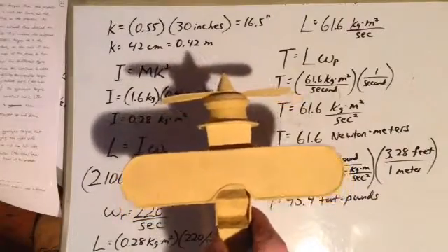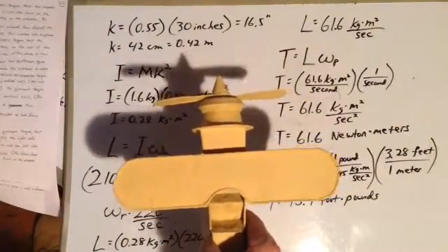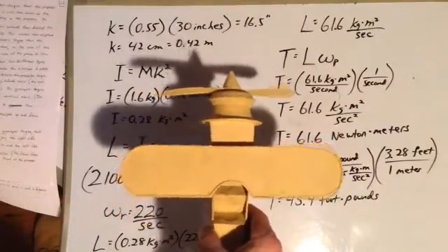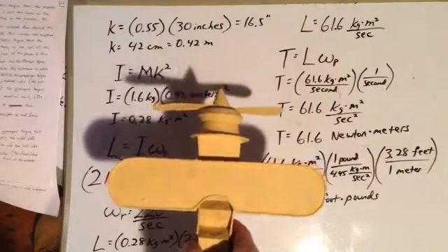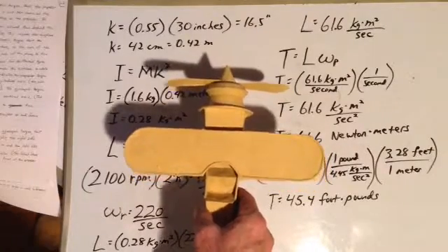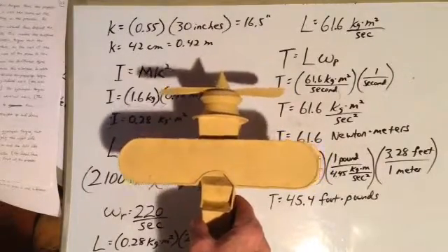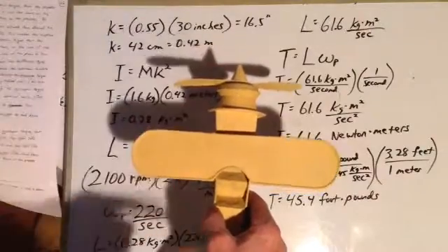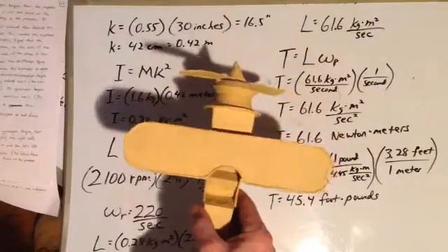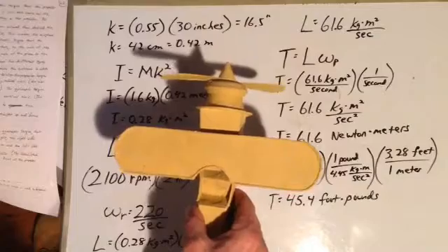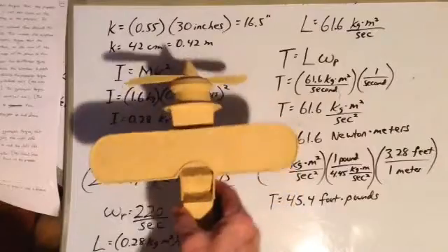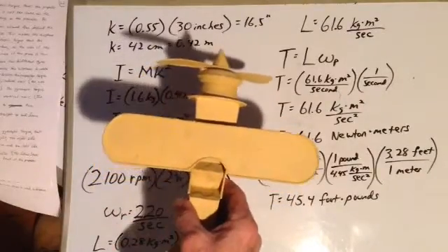So as you can see, these two different types of torque, the torque on the propeller shaft, crankshaft, and the gyroscopic torque, cause the airplane to rotate on two different axes. The engine driving the propeller torque causes the airplane to roll on its longitudinal axis. That's the axis that goes from the nose to the tail. Okay, the gyroscopic torque causes the airplane to yaw on its vertical axis. In other words, turn to the right, the axis that goes straight up through the airplane.